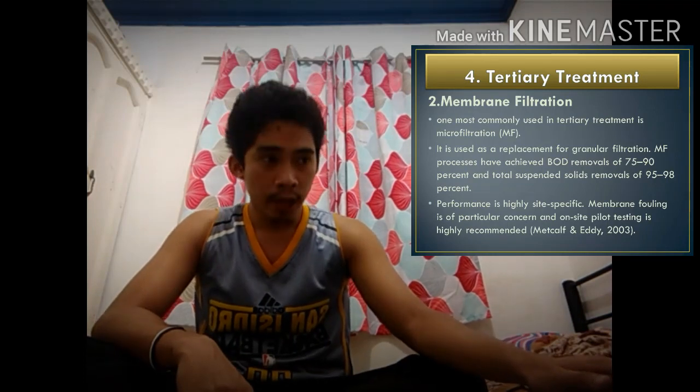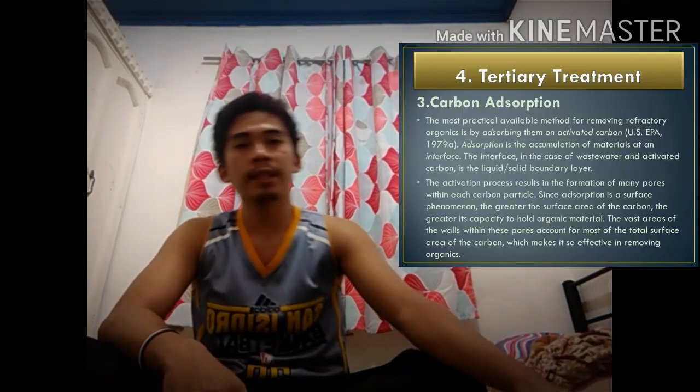The second process is the membrane filtration. One most commonly used in tertiary treatment is microfiltration. It is used as replacement for granular filtration. Microfiltration processes have achieved BOD removal of 75 to 90% and total suspended solids removal of 95 to 98%. The third process of a tertiary treatment is carbon adsorption.